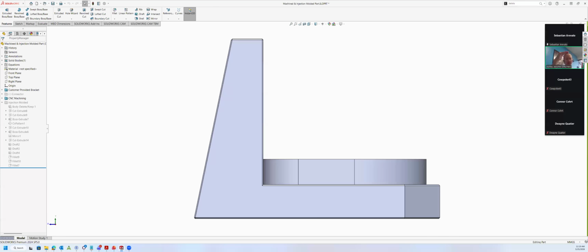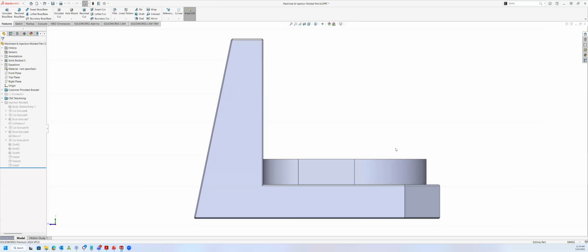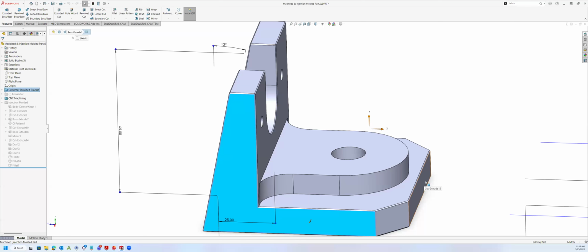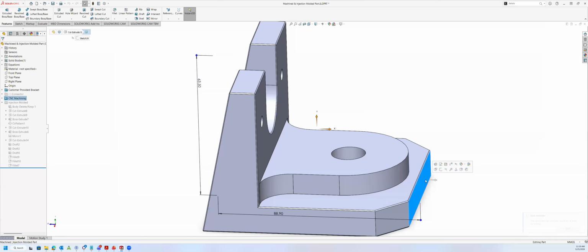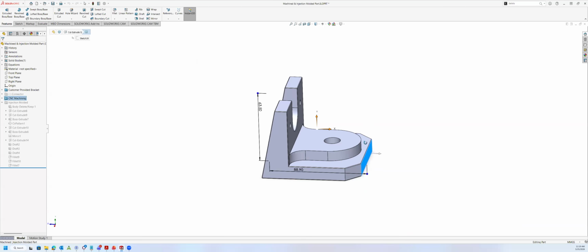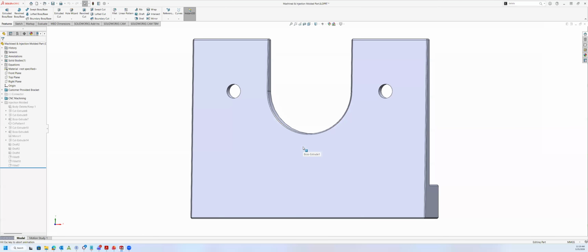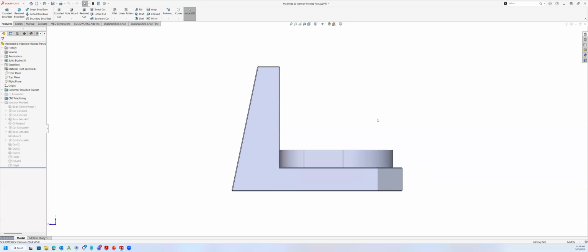Yeah, so how we would CNC this is we would start with a standard off-the-shelf block that is of this size. So what I did when I was reducing the overall length is that I just reduced it to a standard block size that we could buy off the shelf. From there, we would do our first operation, which is just a pass of the overall profile. From there, we would then do a secondary operation to machine in this angle.